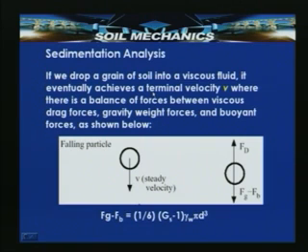The gravity weight forces, because it is in a fluid medium, the buoyant weight forces will come into picture. Suppose you consider a falling particle with a steady velocity V. It has got forces: one force is the drag force which is acting upwards, and the other is the net force, which is the difference of the gravity weight force of the particle minus the buoyant weight.